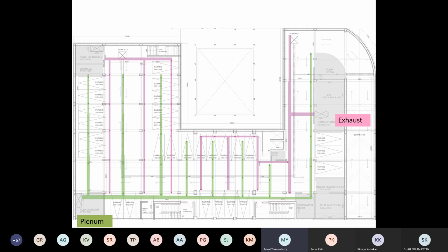So you imagine you have a secondary exhaust duct going above, and you have a column. From that column, you have to give a branch and bring that duct down on the column, and you will have to give a spout with a kind of jali there, so that while I'm sucking the air in, at least it will remove, suppose there are papers lying there, or someone has thrown a cigarette that is still burning, I don't want my duct to be on fire. So everything will be protected by giving that jali.